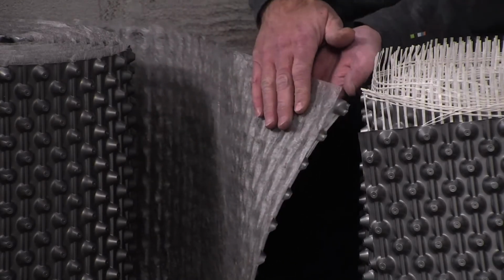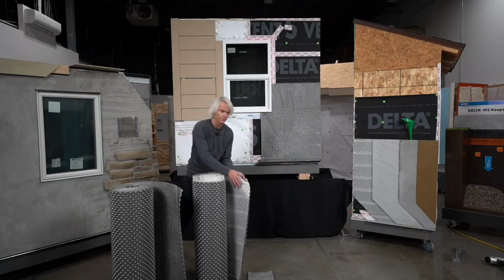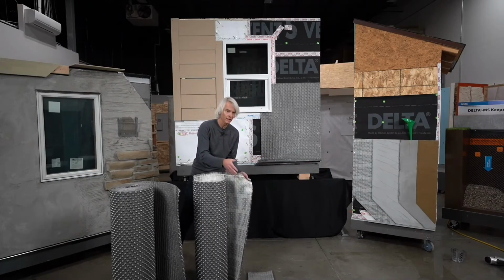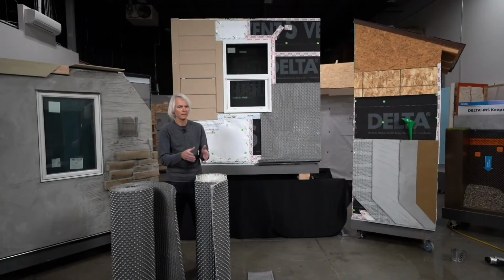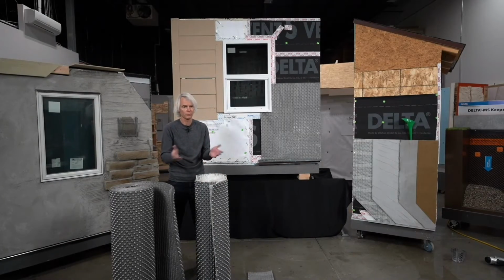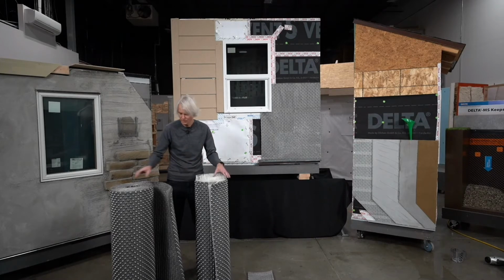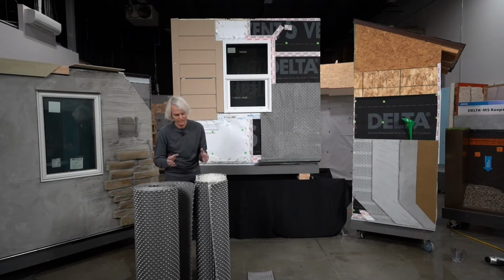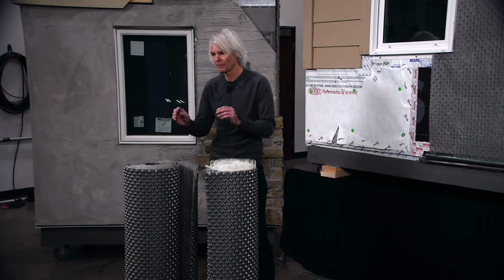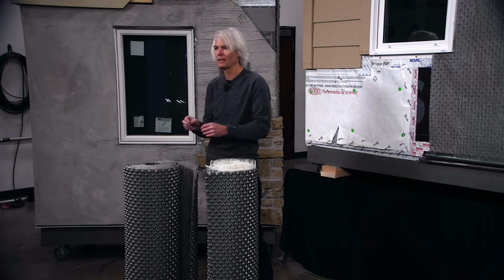It comes with the fiberglass component, and it also comes with this very unique, lightweight, cuts-with-the-scissors integrated lath. We've also seen it cut into strips, 50-foot-long strips, basically a 4-inch by 50-foot strip, used behind wood-based siding materials or panel products to make a rain screen as well. So it's been fun. We love to talk about rain screens here at CI Live, and this is a very interesting application. We talk about rain screens and particularly masonry claddings.